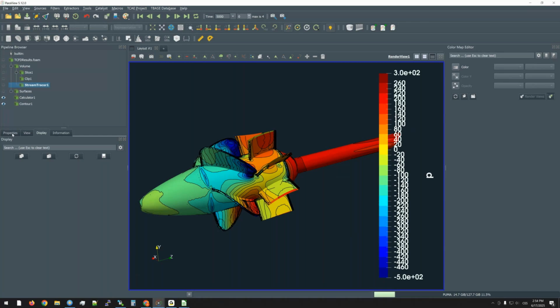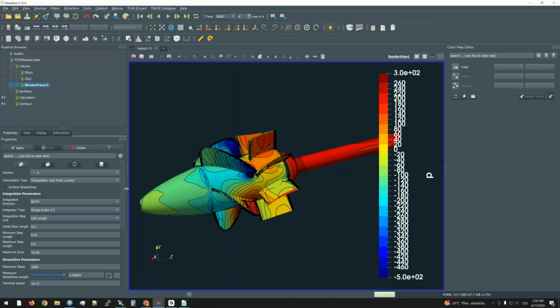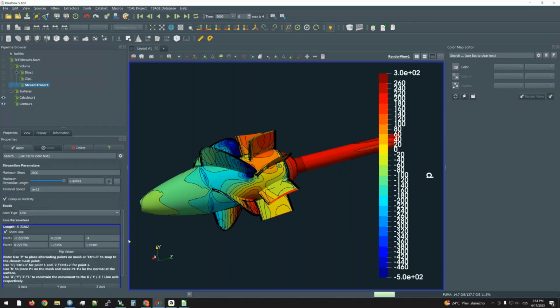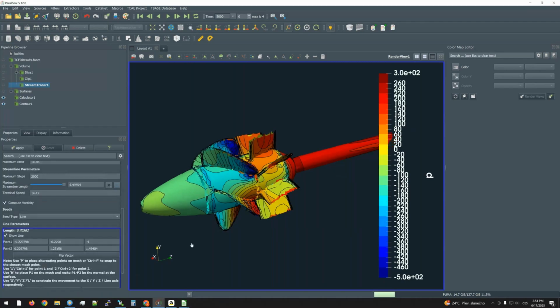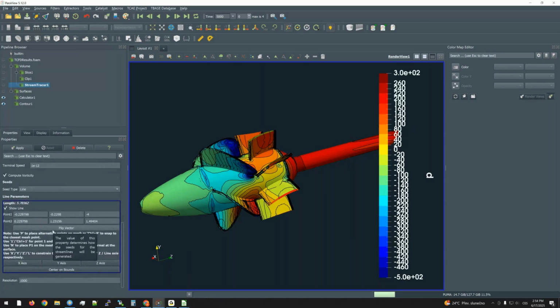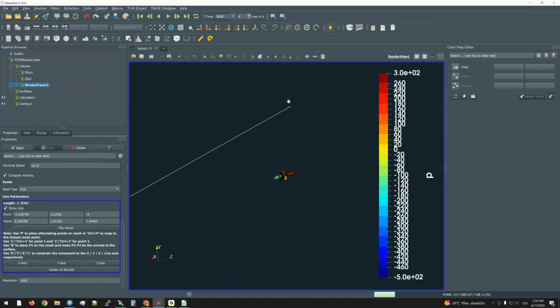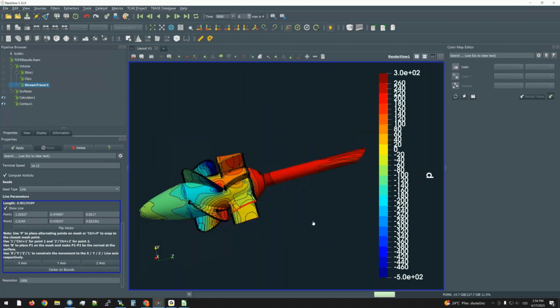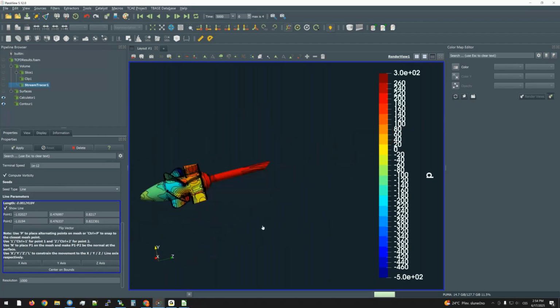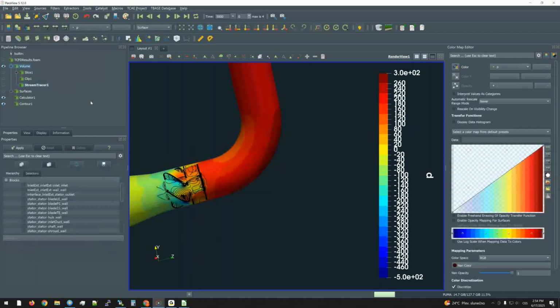And if you go to the properties, you define the stream tracer. Stream tracer or streamlines are defined based on some random seed of points from which the streamlines are evaluated. You have two options. First, to create a source by the line. So for example, if I place, sorry, I need to place this line into my volume. So I will visualize also the volume.